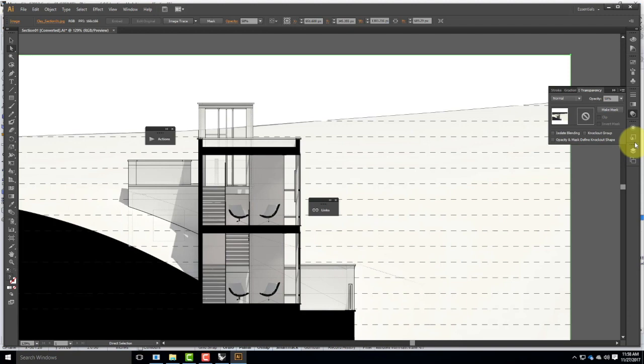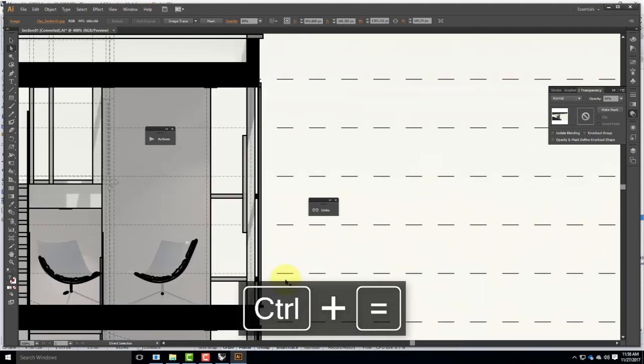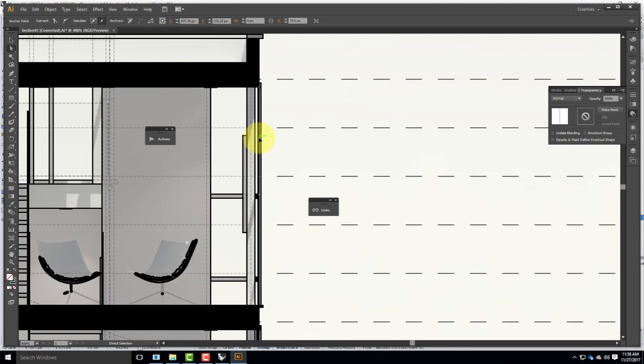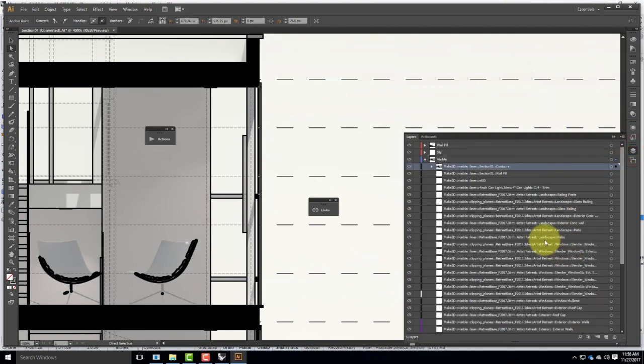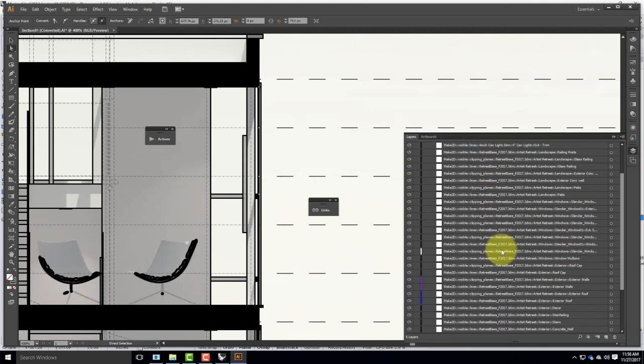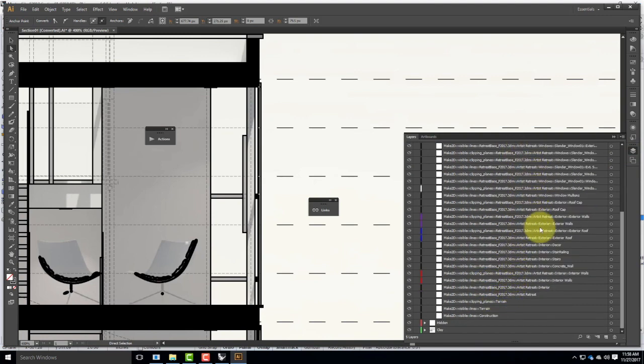I didn't take it into AutoCAD, right? It's just a little bit of tweaking, and filling in the sections make this relatively easy. But if I wanted to make it a little bit finer quality, I could come in and, like these glass pieces, I could really fine tune those line weights so they're not so thick, and it would read that much better. Those are usually available as one of these layers. If you go through and find it, one of these slender window, probably window glass layers in here somewhere, is probably it. I can't find them right now, but it would be relatively easy to select it and go from there.